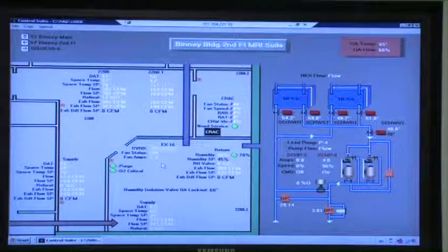This is RH valve, that's your humidity valve, correct? It's not a reheat, so it might be worthwhile making it HUM instead of RH. Yeah, that's a good small point. It's a relative humidity valve, the humidifier valve. It could be interpreted as reheat. It could be interpreted either way. Yeah, let's put that down.